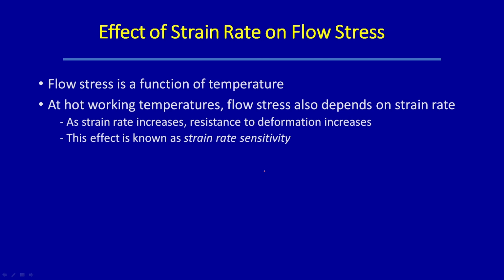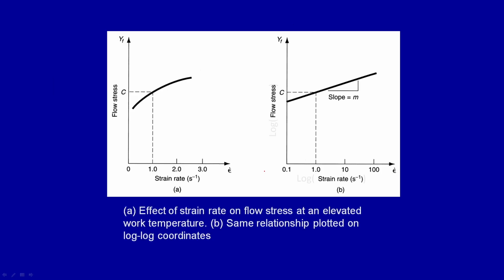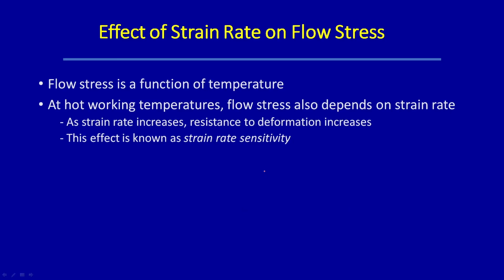And it has been found that as the strain rate increases, the resistance to deformation increases, and this effect is known as strain rate sensitivity. How does it depend? Well, strain rate sensitivity is calculated using this equation. I already showed you that sigma_t is equal to C epsilon dot to the power m, where m is the strain rate sensitivity.